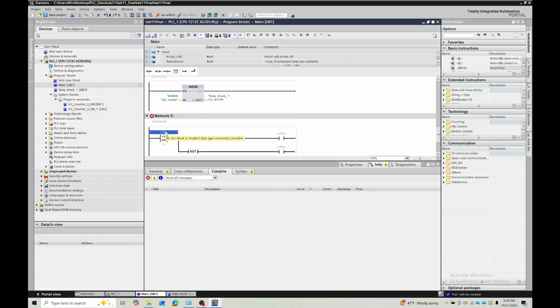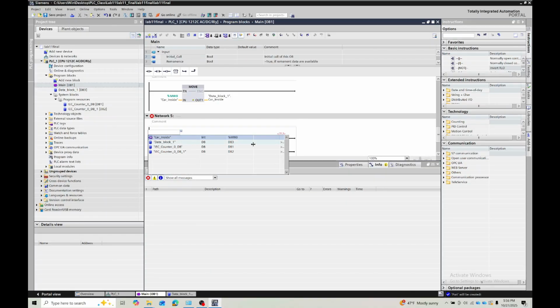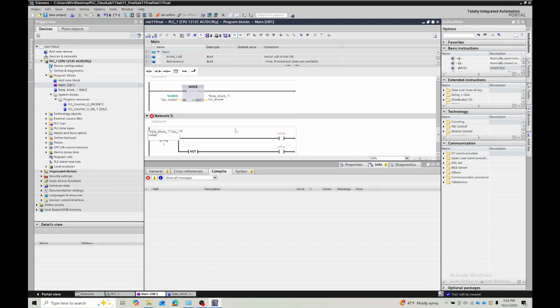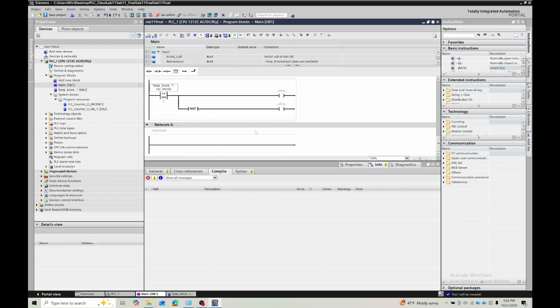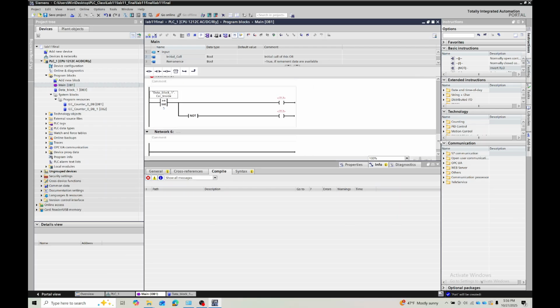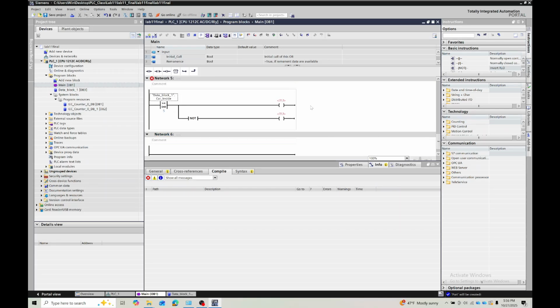And that should be data block car inside. Am I right? So it's the same thing. You go to the data block, then see which one. This is not the right one. This is a memory, so it should be this one. So data block car inside, which is a data block, and save how many cars I have inside. So it's compared with 5. Is that greater? If that's greater than 5, what we should do, we should actually say this is full, right?